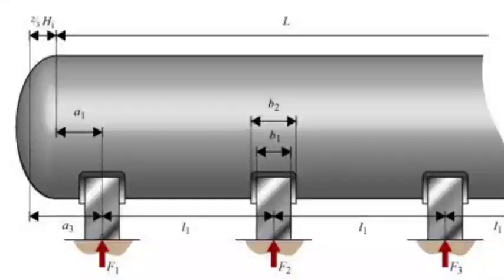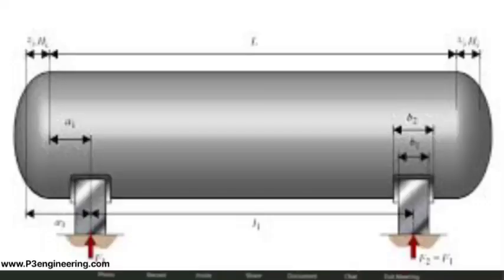Yeah, correct. Normally, with two saddles, we place them at a point from the end, and whatever the remaining distance between these two saddles, in between that we used to keep this third one. Same method I also used to follow: the tan line to tan line distance divided by the number of saddles. We consider that all the loads will be distributed equally on all three. But in PVElite, this third saddle is new, means recent.